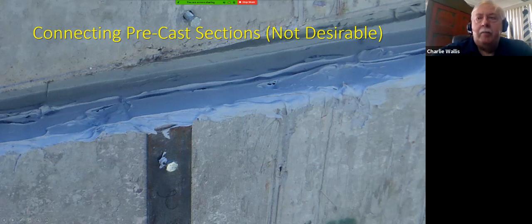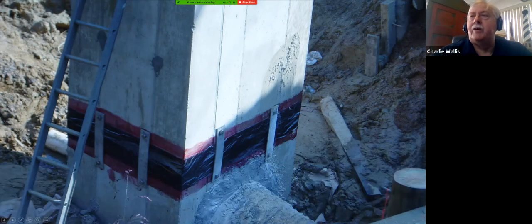And there was just one strap that was going to be used. So we had the engineer look at it, and it turned out they needed 2 straps on each face. So we also had them put 2 straps on, and we also had them put mastic around the entire joint too. And also with the precast riser, the opening wasn't custom made for this spillway pipe that was inserted. So it's brick and parged to try to make it watertight, but this isn't as durable as if it was cast in place properly.